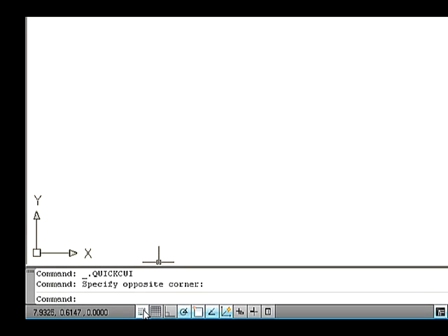Status bar. The status bar has been updated to include some new powerful tools and improve efficiency. You can choose to view text or icons for the standard settings, such as OSNAP, Grid, and Dynamic Input. The new interface makes it easier to tell which settings are on, which is much appreciated. Right-clicking many of these options, such as Polar or OSNAP, also enables you to make quick work changing the settings, thus saving you an extra click.